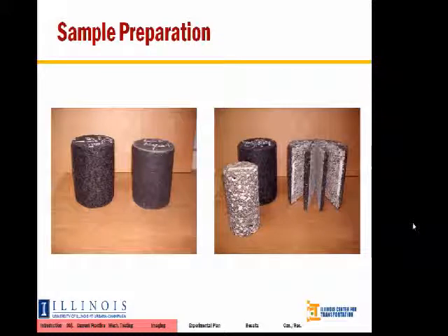This should give you a better sense of what is taking place. On the left, you've got 2 gyratory specimens before any preparation is done. On the right-hand side of the screen, you've got the 2 prepared specimens. Okay, the one cut and cored to go for mechanical testing, and the one on the far right of the screen sliced vertically, physically sliced to be able to capture 2D or planar images from that specimen.